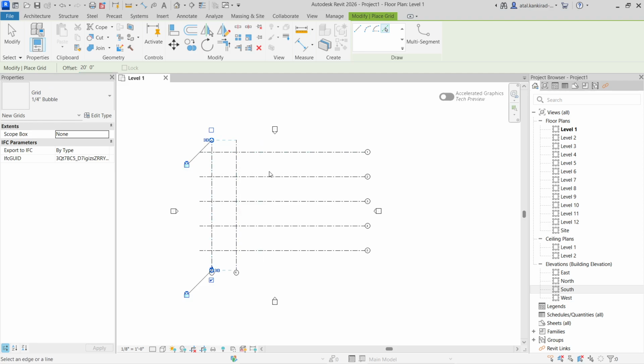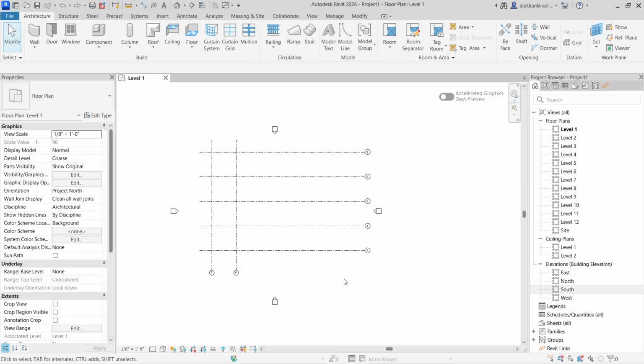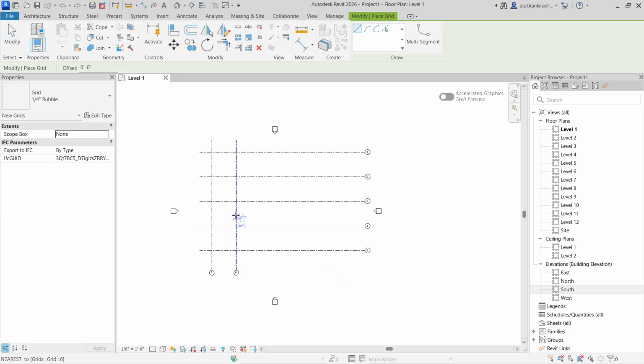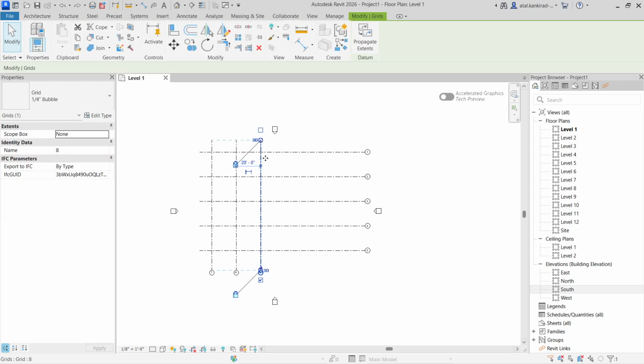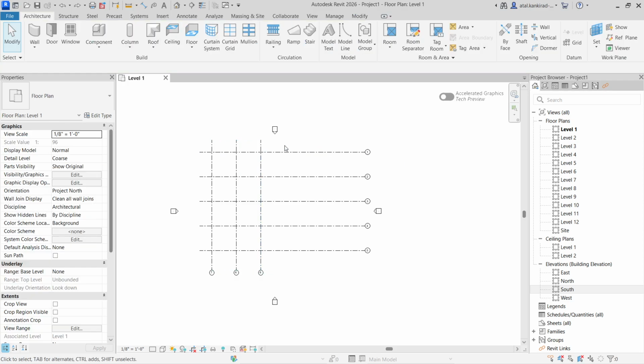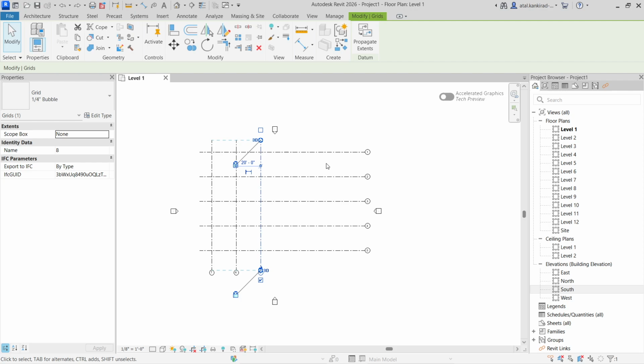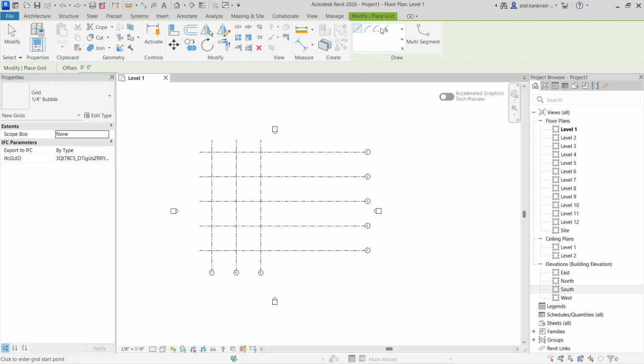So this is how our grids are now placed. You can see we can place any grid here. Again, we can draw this, and we can select it. Also, to create the same kind of grid, we have the Create Similar option as well. If you select any grid or anything in Revit and just type CS, that is Create Similar, it will turn on the same command.